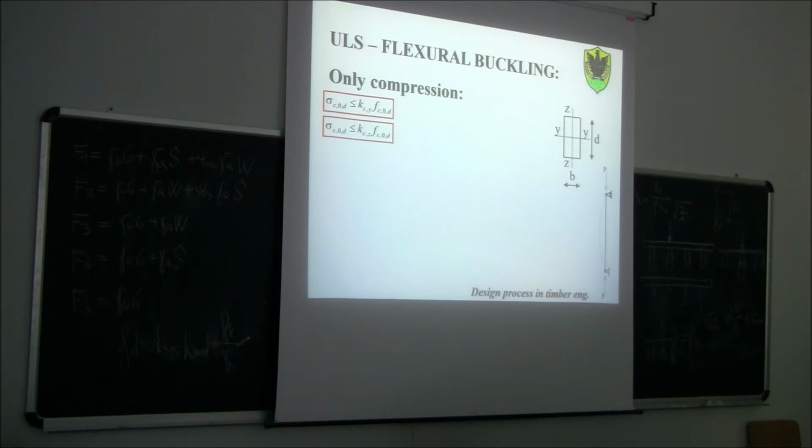So the original omega method was, first of all, I calculate the slenderness ratio. Then, based on the slenderness ratio, I calculate omega, which is a certain function of lambda. Then I run this formula, increasing the sigma to take into account the buckling problem. And then I check that the design inequality with the sigma permissible is always satisfied. This was what I studied several years ago. I call it the omega method, or gamma method.